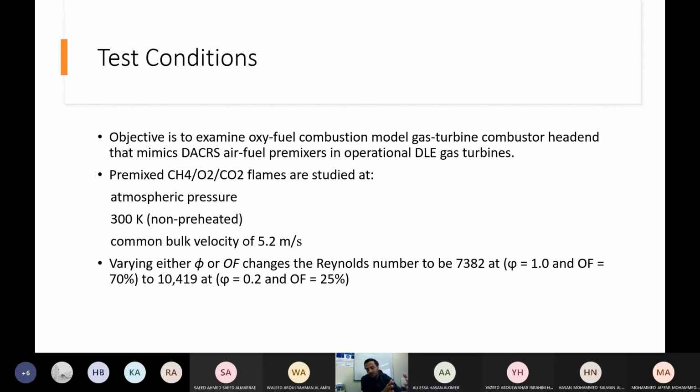Just those are some testing of those burners in our lab in a model combustor, but this model combustor can generate power within the same range of industrial gas turbine per unit volume per atmospheric pressure. Usually all of these tests, guys, as I told you before, in gas turbine we design the burner in order to have minimum pressure drop, or almost the pressure drop across the combustor is fixed or constant. Delta P is equal to half rho V squared, and the density is for the mixture, which almost is the density of the air, because air actually is the dominating species, so which is constant.